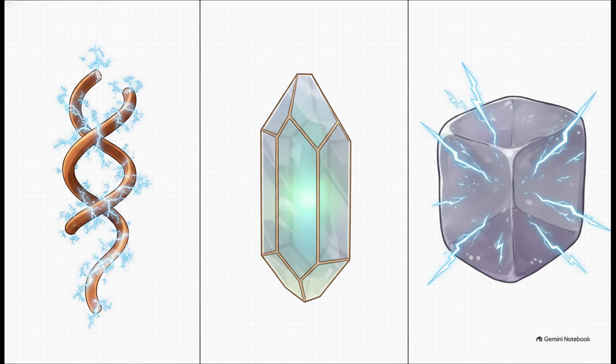These offer incredibly high resistivity. We're talking in the order of 10^10 up to 10^12 ohm centimeters. It's a massive, massive barrier. But then, right in the balance, we have our semiconductors, most famously silicon and germanium. Their conductivity falls exactly in the middle.